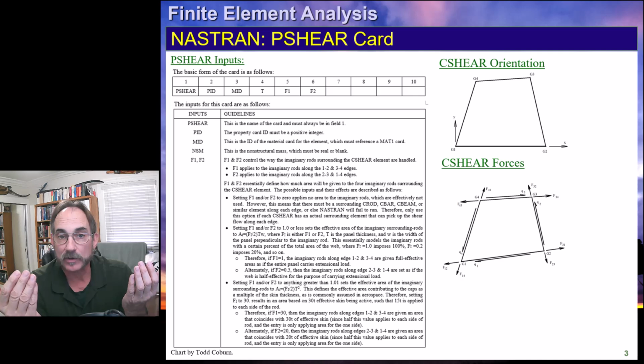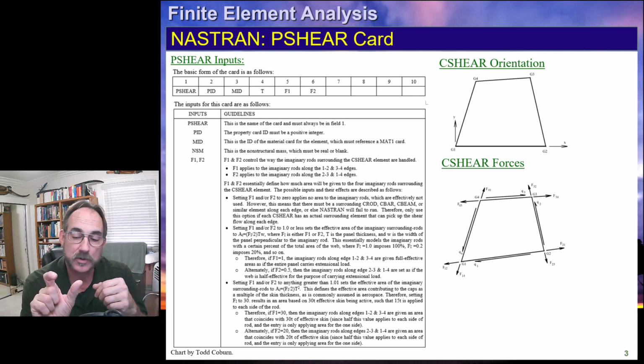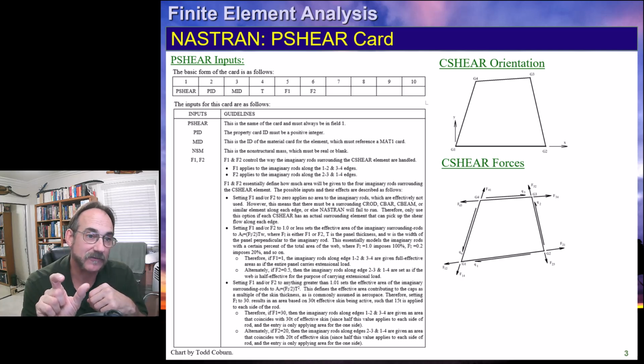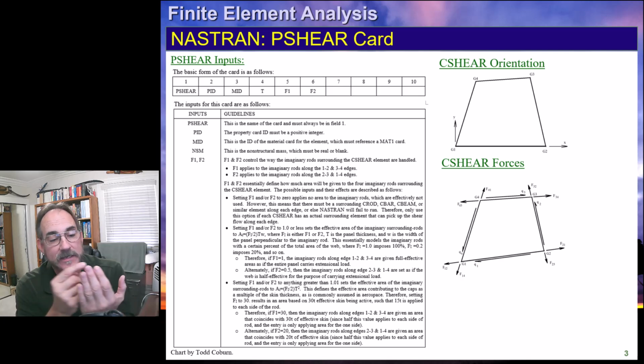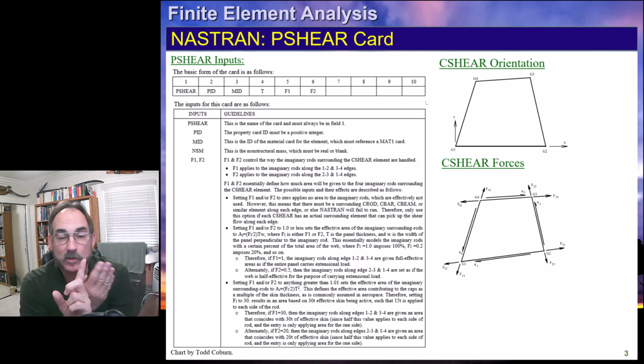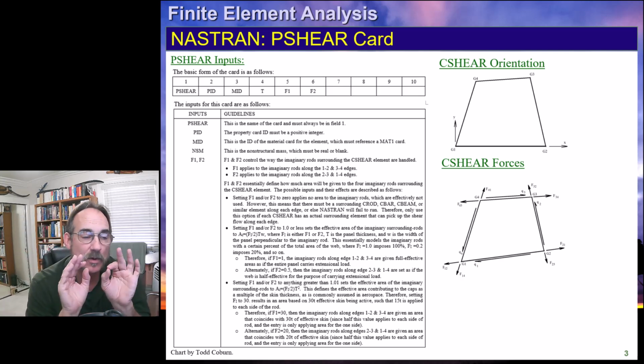Like a common rule of thumb is 30T, and if you set that to 30, that will give you 30T of effective width of skin, which means half of 30T for each panel, since an edge stiffener will have only half of the effective width from that one panel and half from whatever panel is on the other side. So that's the way it models it.